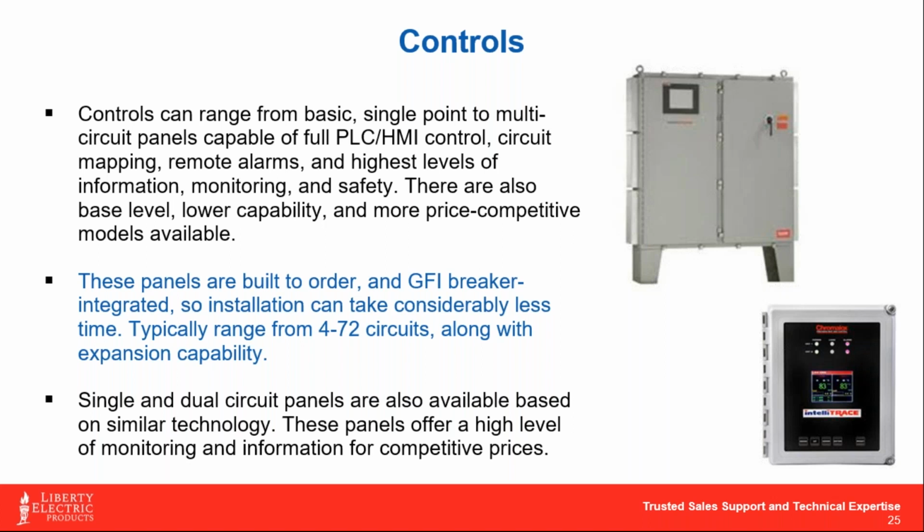So on the high end of things, we've got fully integrated heat trace panels that are breaker loaded. You can almost look at them like they're their own separate load banks. And that's the nice benefit to them, that this is a fully integrated panel that's going to have breakers in it, contactors in it, GFI protection in it, and an HMI touchscreen, so you can access information that goes far and away beyond what standard mechanical based controls are going to give you. You can put alarm options into these things. You can tie circuits together.